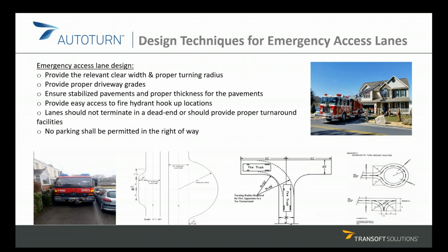Ensure stabilized pavements and proper thickness for the pavements so that even heavy vehicles like the fire trucks can access the location without any difficulties. Provide easy access to the fire hydrant hookup locations. And also the lane should not terminate in a dead end. And if it does so, we should provide proper turnaround facilities like a hammerhead turnaround or proper width for the cul-de-sac so that the vehicle can make a turn without stopping. Also, no parking shall be permitted on the right of way.